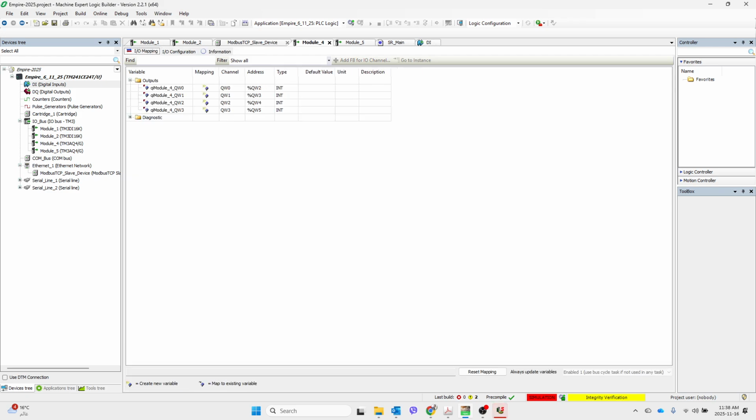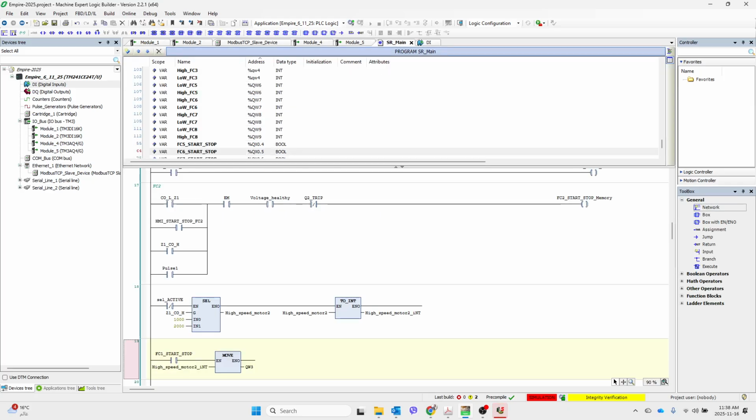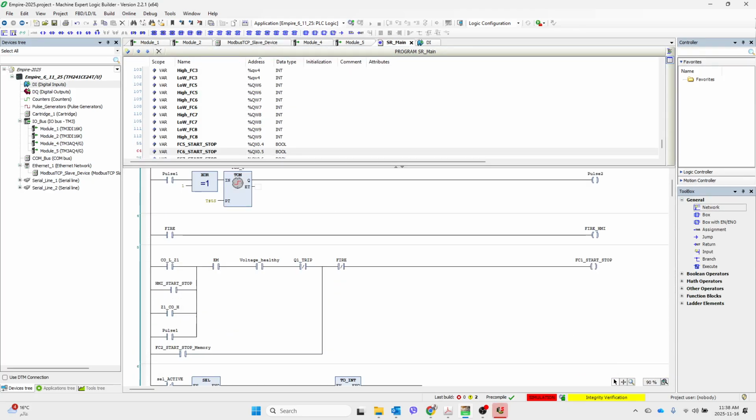We have to configure it and route it to the output of, let's say, we have to put it in memory. We have to write it to the memory, then we will be able to have it on the HMI. This is now the indicated memory. You can see here, the percentage sign indicates the start of the addressing. %MX0.9 indicates the memory mapping for that individual signal.